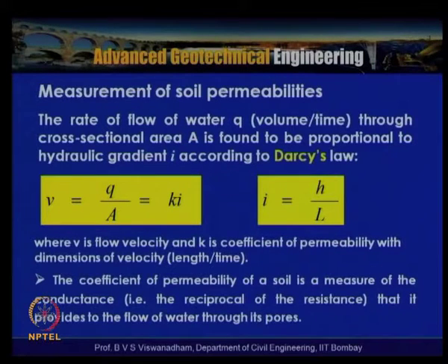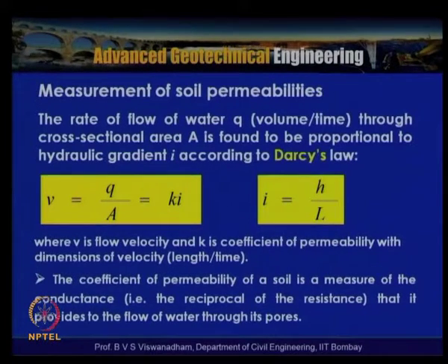So, the measurement of soil permeabilities. We have said that permeability is a property of the soil where different types of soils exhibit different values, and this is used for different applications in civil engineering construction. It will be interesting to know how this permeability is actually measured. The permeability can be measured from indirect methods, or from laboratory tests, or through field tests.